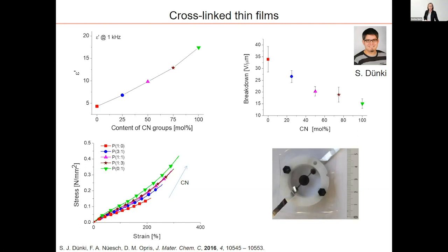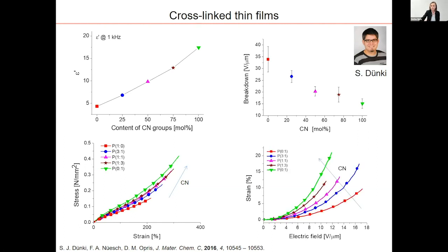And that's what we measure. That's the lateral actuation strain. And this is what is plotted here, lateral actuation strain as a function of the electric field. You can see that with increasing polarity, we have a reduction of the electric field which is needed for the actuation. And for a material which is fully functionalized with polar groups, which has a permittivity of about 18, at 12 volt per micrometer, we have about 20% lateral actuation strain.